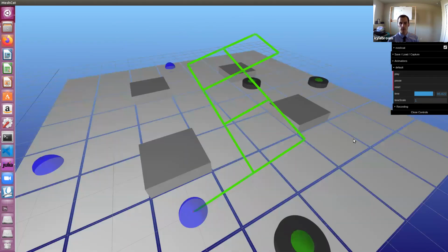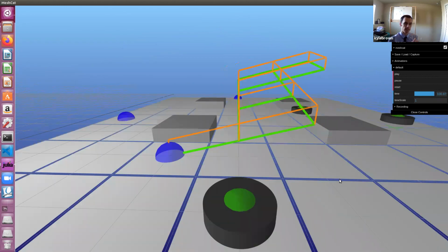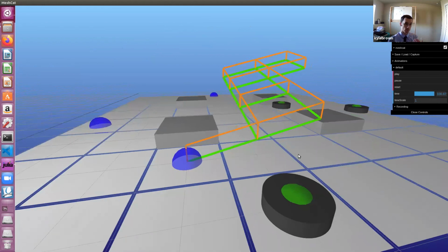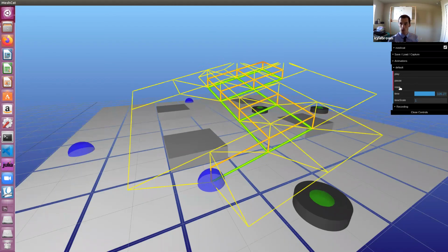Now I'm going to animate a different set of paths, which is the set of all paths that the robot can take to the goal that reach the goal in minimum time or only have one time step of delay. And you can see that is a larger set of paths that can be returned by the algorithm. Because the algorithm can search this larger set of paths on demand when it needs to, it can avoid collision more effectively. If we were to allow 2 time steps of delay, the optimal reachable set grows even larger.